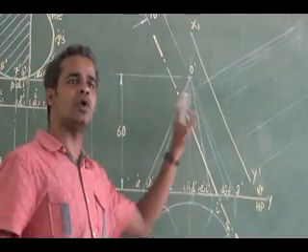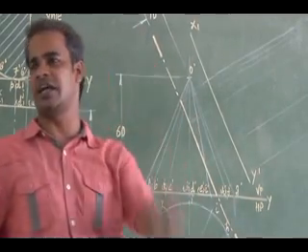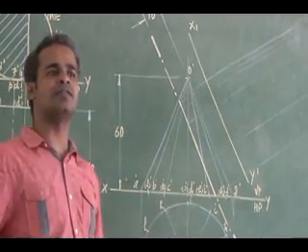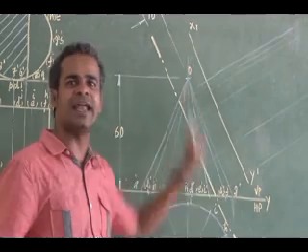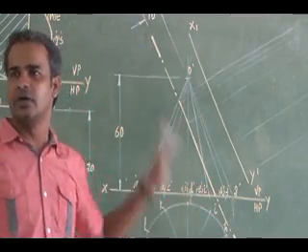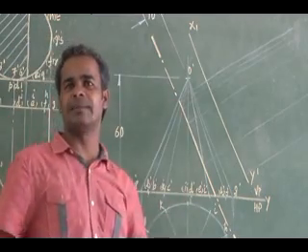Because we are going to get cutting points on the generators. Where the cutting plane cuts the generator, there we have to mark the cutting points. So you try to show the generators in the front view also in 2H pencils. Don't darken it. Then representing the cutting plane.